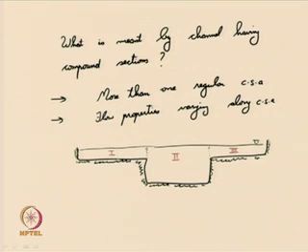Like that, if many types of cross sectional area appear in a single section, such channels are called compound sections or compound channels. A very simple approach is that you can individually compute flow in each of the areas and finally add it up.